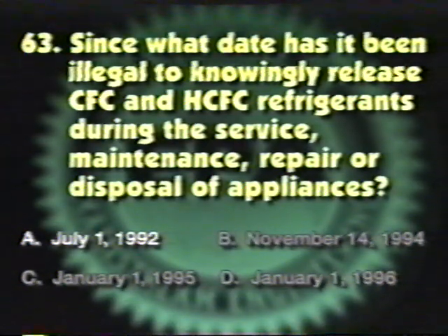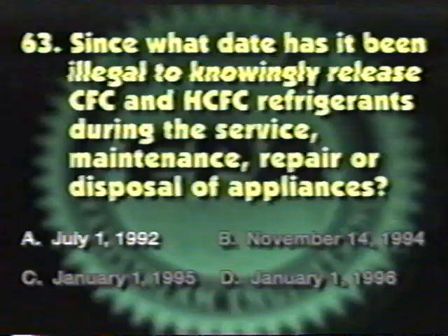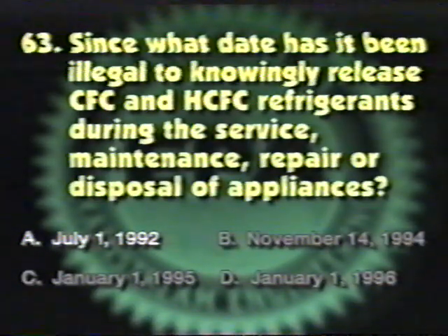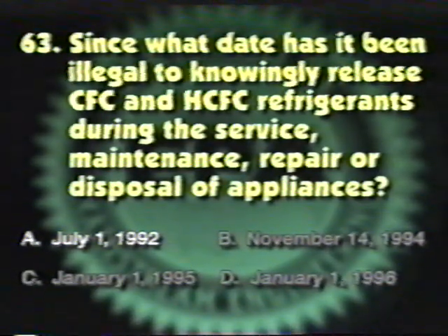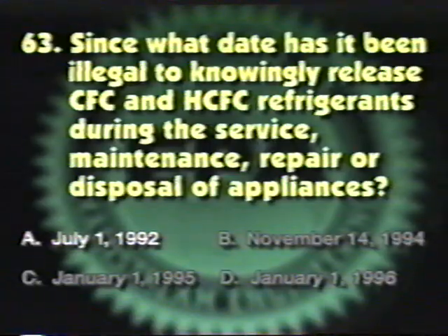The correct answer is A. Effective July 1st, 1992, Section 608 of the Clean Air Act prohibits individuals from knowingly venting ozone-depleting compounds used as refrigerants into the atmosphere when maintaining, servicing, repairing, or disposing of air conditioning or refrigeration equipment.